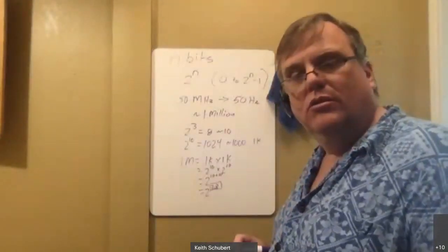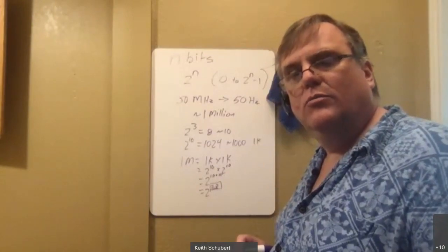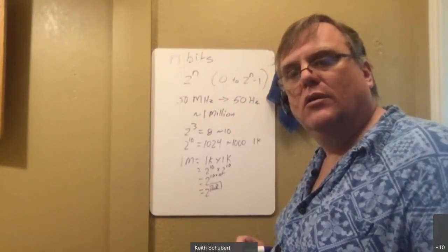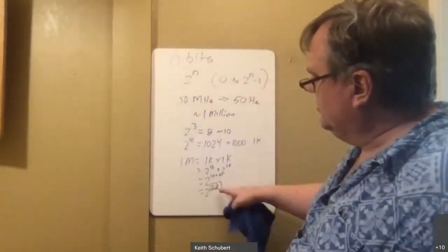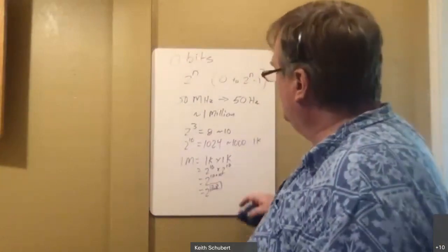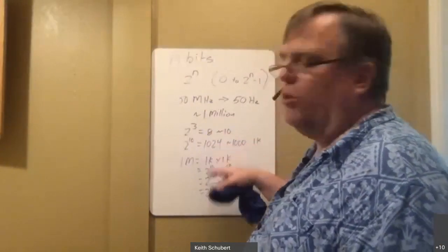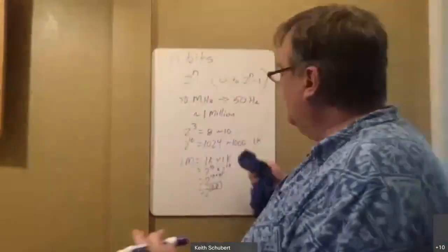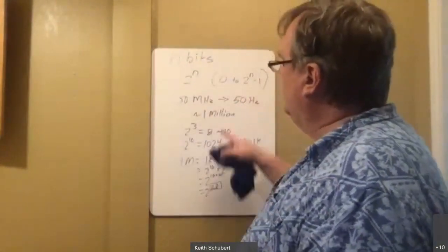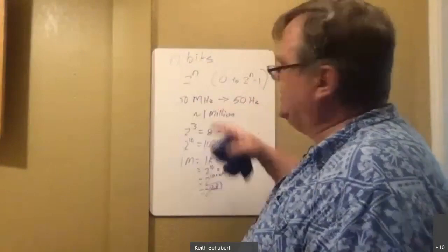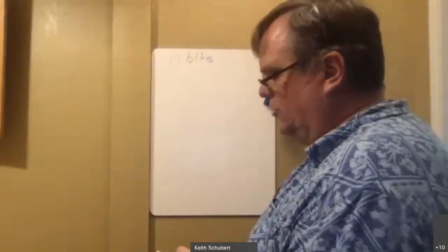So far, so good? Yes. Awesome. All right. So let's consider this. Now I've got 2 to the 20th. So with 2 to the 20th, I've got over 1,000,000. In particular I have 1024 times 1024. So I've got over 1,000,000, and I want something less than that. I can now say, okay, I'm going to build a counter that's a 20-bit counter.